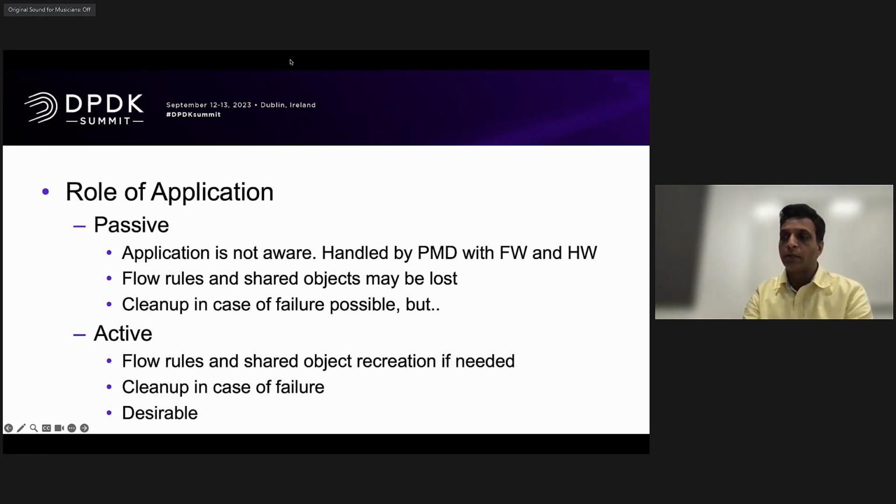Once the driver detects the error, it can trap any control plane or data plane activity. If necessary, it can update the TX and RX handlers with dummy functions so that there's no further activity.